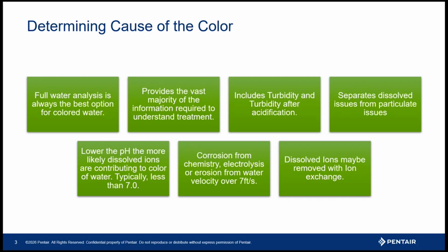You may have electrolysis, and electrolysis may come from infrastructure issues like poor grounding or stray voltage from an electrical system, no matter where in the house. If that's getting to your water supply, that can drive corrosion and some chemistries there. And people using water faster than their plumbing allows.